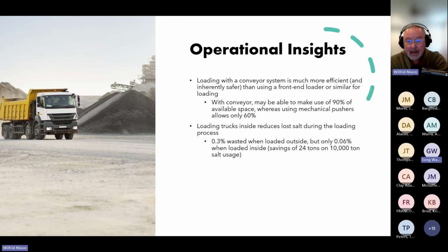There's also some interest in loading trucks inside. Well, it will reduce lost salt. When you load a truck, you do lose some salt. Again, the literature suggests you lose about 0.3% of your salt if you load outside, but only 0.06% if you load inside. To put some numbers on that, what that would mean if you use 10,000 tons of salt from a facility in a year, then by loading inside, you would save 24 tons that would otherwise be wasted if you loaded outside. So it's not a huge